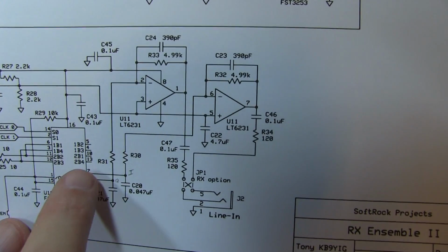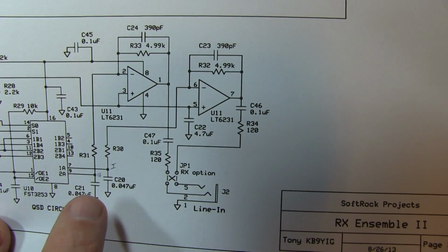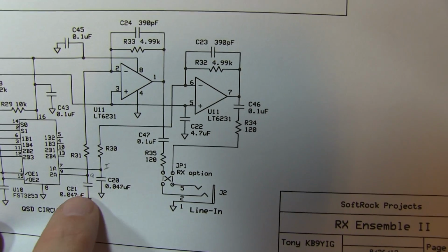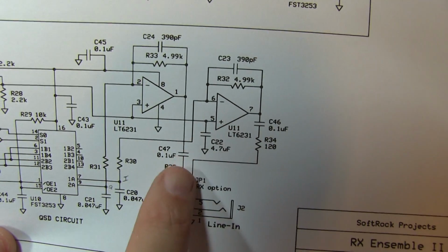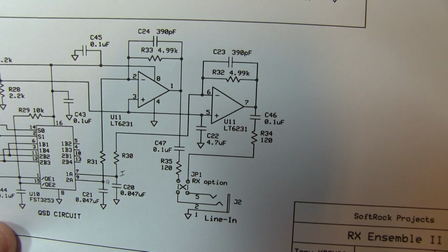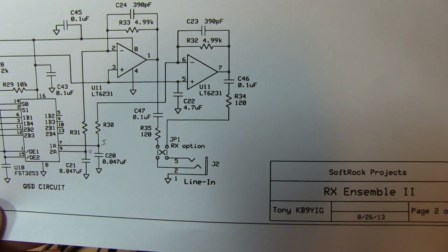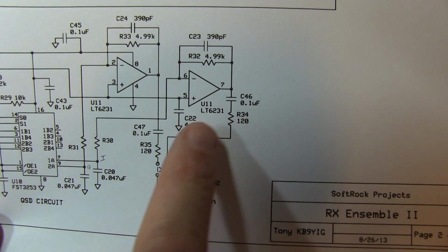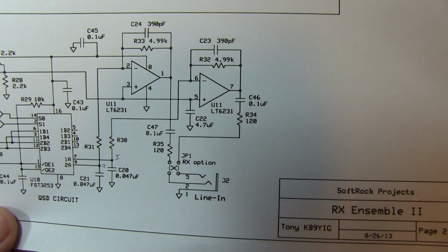Now the I and Q outputs from the Quadrature sampling detector are essentially integrated or low-pass filtered. The I and the Q signals both go into essentially being filtered by this capacitor here, and then through a simple op-amp filter here and here, and those outputs go out to the jack that goes to the audio input of your computer that does the final frequency selection and demodulation. So I'm going to probe on the board these 2 resistors here, with the signal coming in, and we'll go take a look to be sure that the rest of the circuit is working.